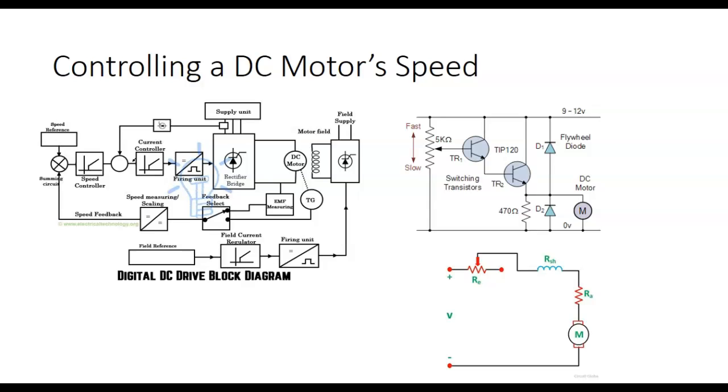So I just had relays that would either short the resistor out or put them in there, and they were 5-speed cranes. We can use resistors. We could use a rheostat, or a pot being used as a rheostat. But you've got to understand that your motor's out here running. This guy right here has an I squared R loss, so these are not going to be used to run very, very high horsepower motors.